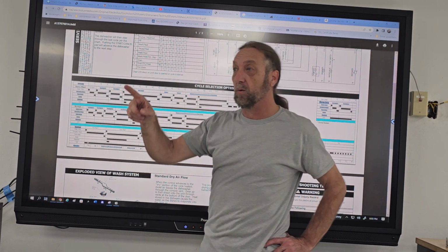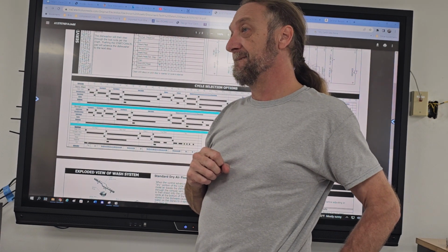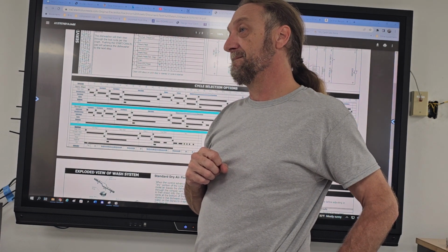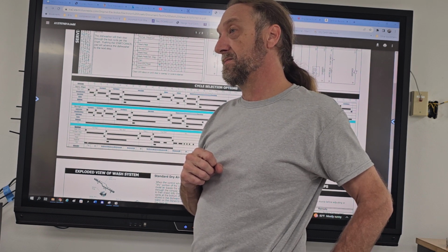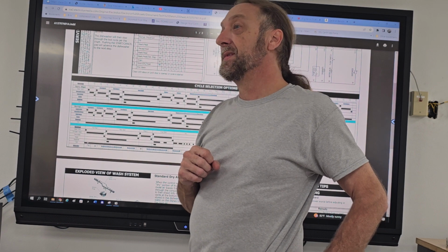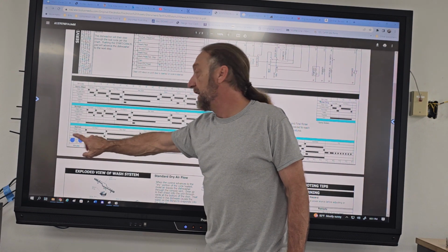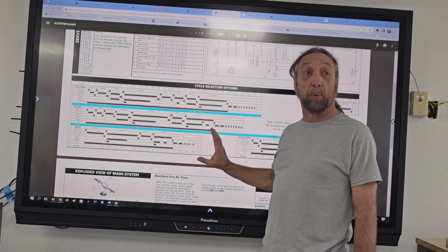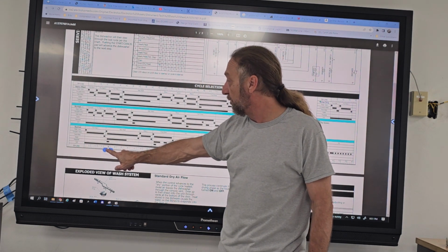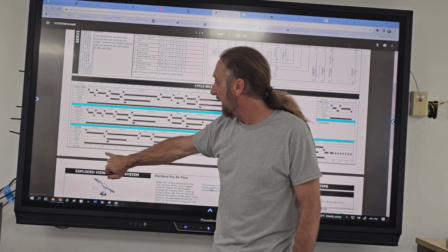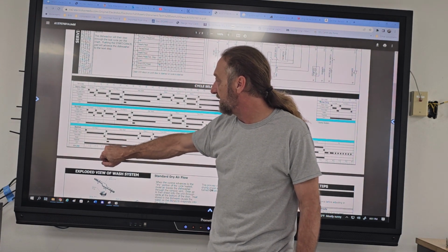You got a question? So you're saying based upon the time cycles, it's only important to test for voltage within this range, when something's open or closed or alive, basically. Well, what I need to do is look at the heater and find out where in this cycle the heater is supposed to be turned on. Because when you turn on a dishwasher, my heater doesn't come on till after what? What time am I on this timeline that the heater circuit is energized?